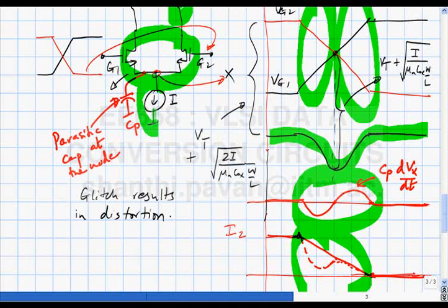And thanks to the cascode, that is possible because, for matching reasons, you need the lower transistor to be huge, correct? If you didn't have a cascode, you have a double whammy. First of all, the DC output impedance is smaller.